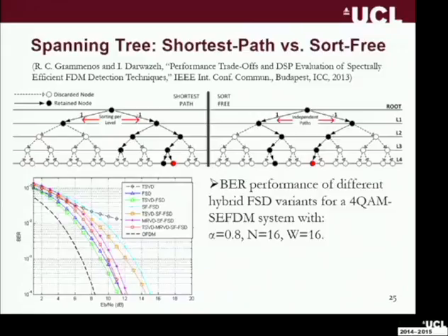So what we did there, the modified real value decomposition didn't have any additional complexity, so that was kind of like a bonus. But the sort-free version actually did simplify over the original fixed sphere decoder algorithm. So this is an example of how we were able to basically simplify the algorithm without degrading the bit error rate by using other novel schemes with the algorithm. So, kind of algorithm optimization, if you like. Okay?